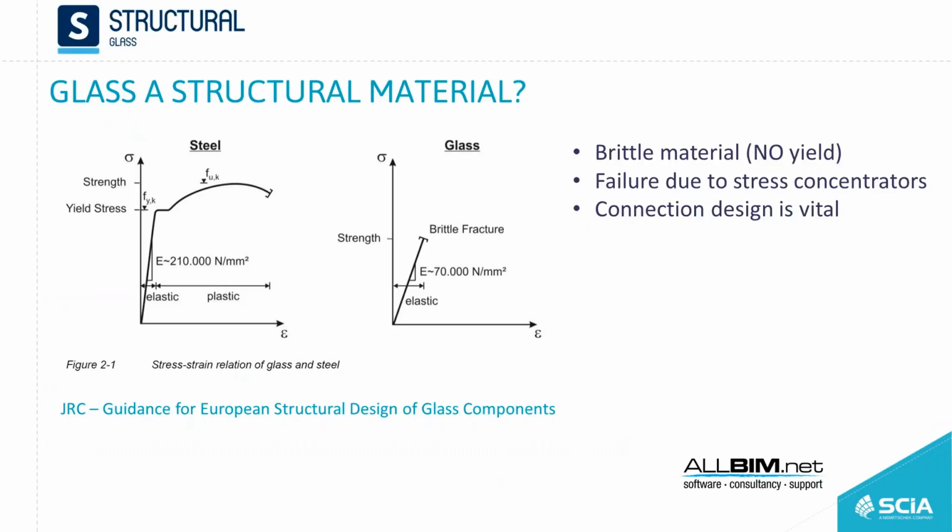Now we will go to glass, which is quite daring to say it's a structural material because of its lack of redundancy. Glass is an elastic material. So when we think of elastic material, we can compare it with steel or timber, where we have the possibility of yielding. So we can have plastic deformations and redistribution of tension. So in case we under-evaluate the loads, we can have distribution in plastic domains, and this way we can ensure some redundancy to the structure.